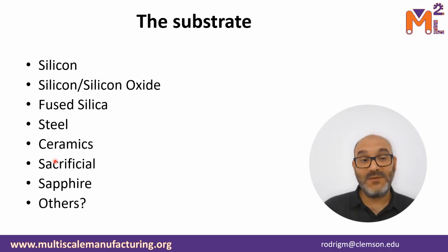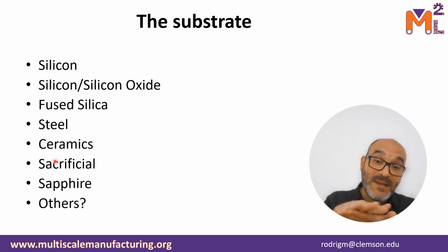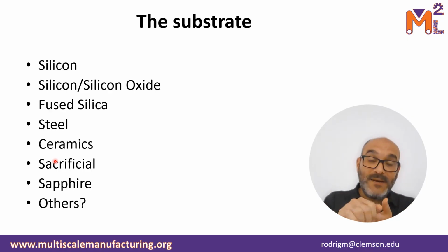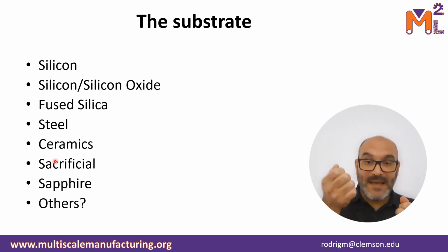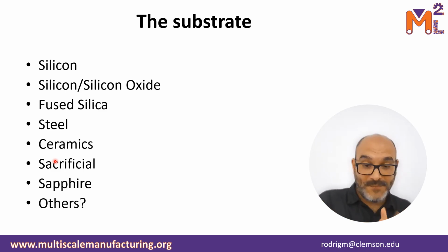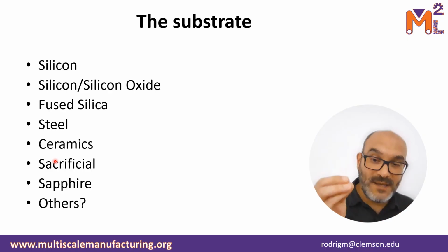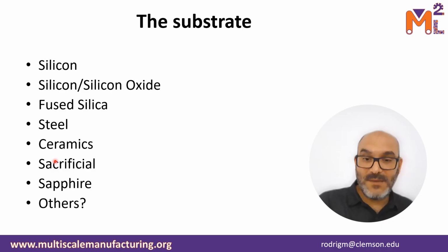In some processes, we will actually do our photolithography process on a thin film of polyester or PET, right? After we do the process, we will actually peel that PET film out of the SU8 structures, such that we only carbonize the SU8. We do not heat treat the PET.